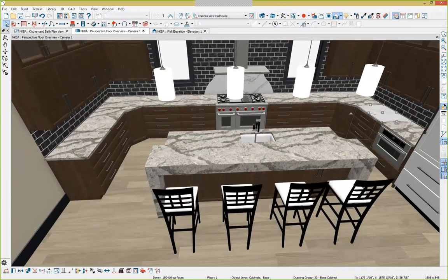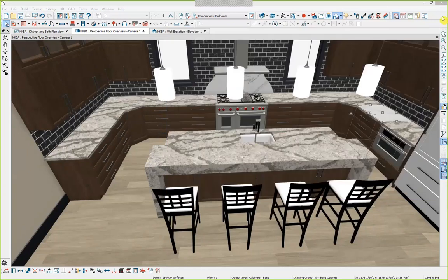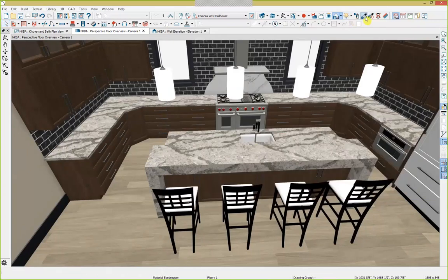You'll recall that the material from the photo is the white material. I'm going to use that object eyedropper tool we've been using. Select that material from the backsplash. Notice how in the bottom left-hand corner my distribution mode is room wide. So if I select this countertop right here, it's going to change that material anywhere that it's at in the plan.